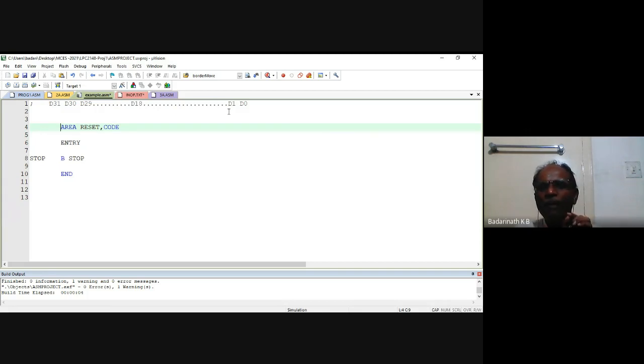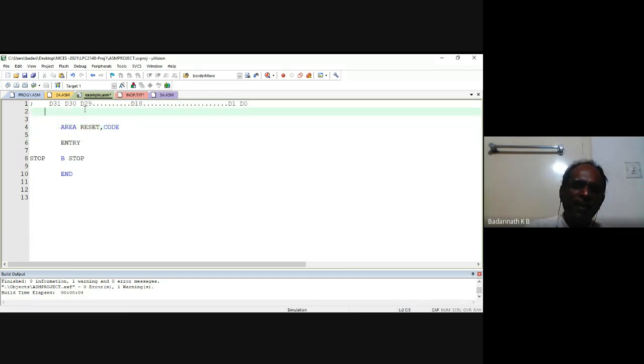In preparing an AND mask, there is a little confusion. Whichever bit you want to make 0, you have to make 0, and the other bits you have to make 1. I have to remember the AND operation, make those bits 0 and all other bits 1. It's a little confusing. Is there a way to make it easy?